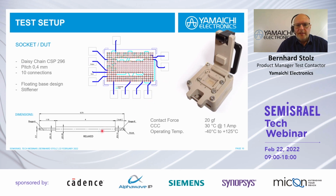The pin itself is a pin which is double side ended. Means there's a spring inside. Both plungers are spring loaded, and so the length in relaxed position is 5.7 millimeters. In working position, we have 5.05 millimeters. The force is 20 grams.